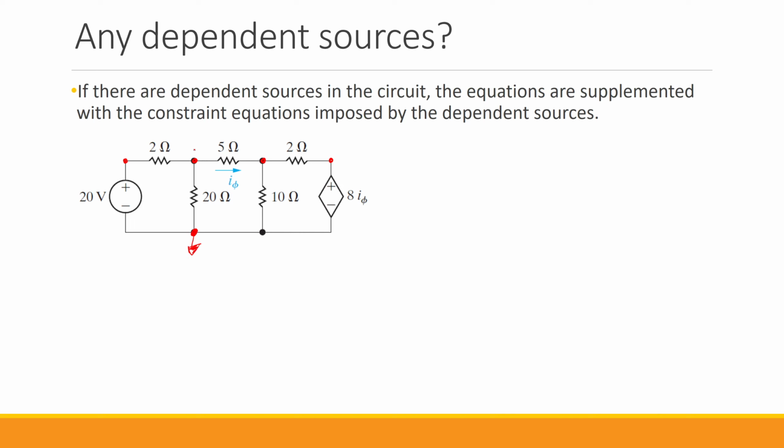And then I assign the numbers for the individual nodes. I say this is V1, and this one is V2. Now that we have this, we need to write down the KCL based on the currents leaving these nodes and going through the connected elements. But we don't define any individual current variable. We use the node voltages to write those currents.